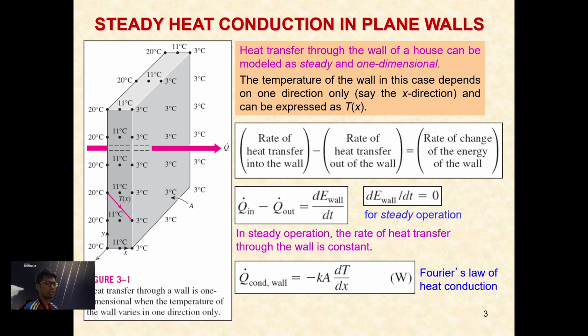Okay, the flow of the heat transfer is always constant, so we call it steady. The point is it is not a function of time, to make it easy to understand what steady is. And what is one-dimensional? One-dimensional for heat transfer, it is only one direction.